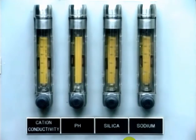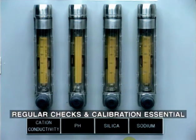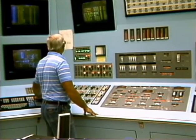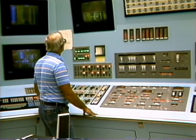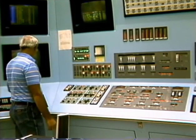In many plants, continuous automatic analysis is performed and displayed on a panel. Of course, in order for the readings to be meaningful, it's essential that the equipment be regularly checked and calibrated. The operator must always be aware of the actual boiler water conditions at any time and how this compares with the established limits of operation. He must also know what action to take in case the conditions move drastically outside the limits.